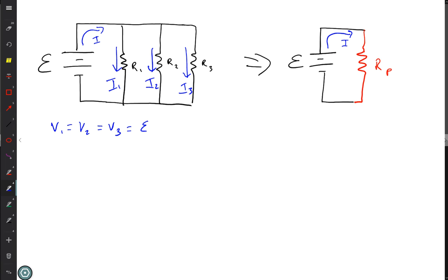which means I can calculate the currents. The total current is split up 3 ways. If I start with 100 electrons and 50 go in the first pathway and 30 go in the second, how many go in the third? 20, right? Because electrons aren't being created or destroyed, they have to go through. So since current is charge per second, the current has to add up. So I have to have I equals I1 plus I2 plus I3.